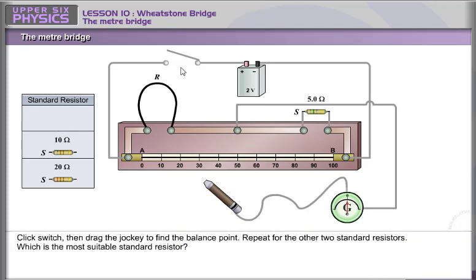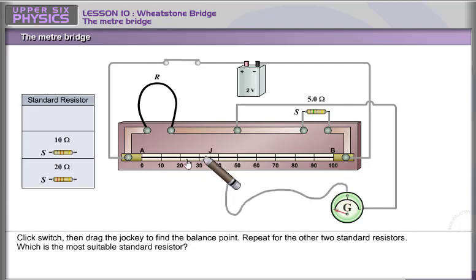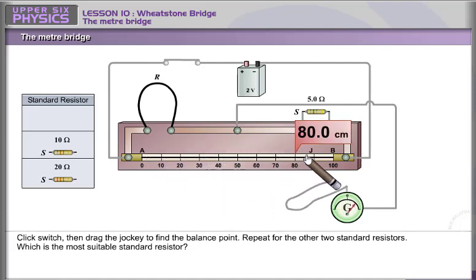Click Switch, then drag the jockey to find the balance point. Repeat for the other two standard resistors. Which is the most suitable standard resistor?